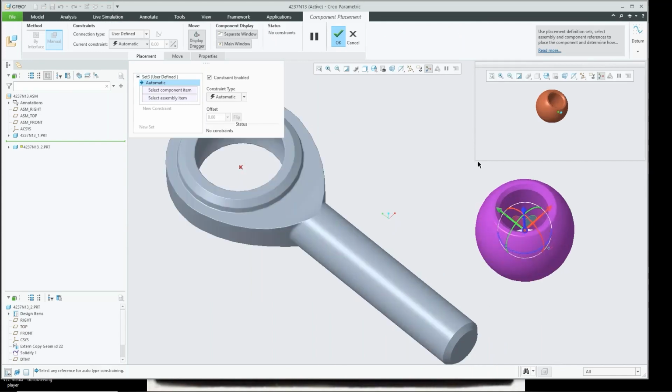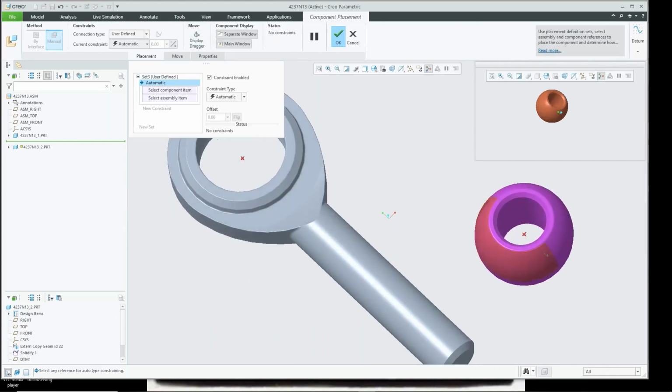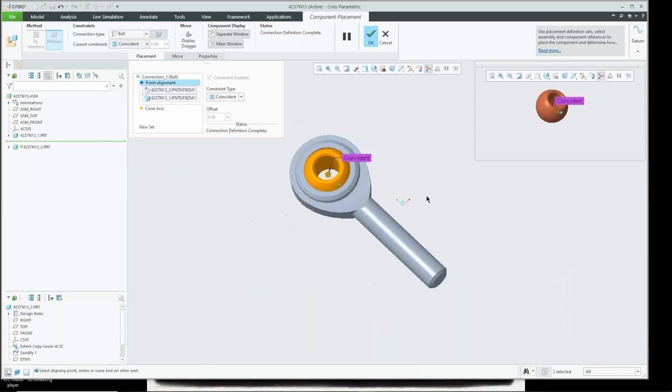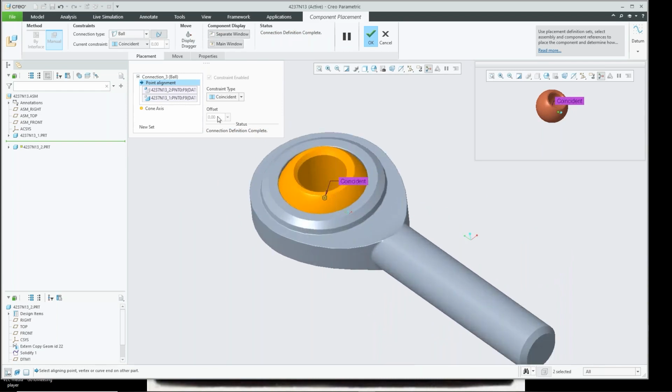the second part. Turn off the 3D dragger. And once again, I'm going to change this to a ball joint. I'm going to go from this point to that point. There it is. Now, once again, it's happy, but one of the things that I use old school wise is inside of here, I want this thing to rotate so I can see how it moves. If I hold down the Control and the Alt key with the middle mouse button, I can rotate that part all by itself.